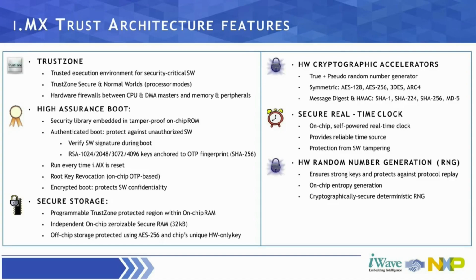As I told you, we are maintainers of our i.MX and Layerscape architecture, and we are contributing to the open source and updating it with new systems on chip. We are updating the support for OP-TEE. The iAssurance boot, this is our secure boot. We do support RSA, ECDSA.